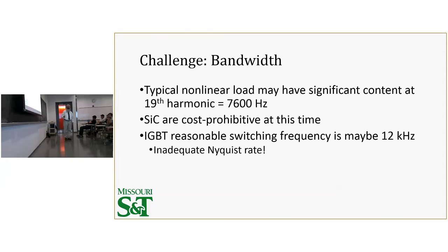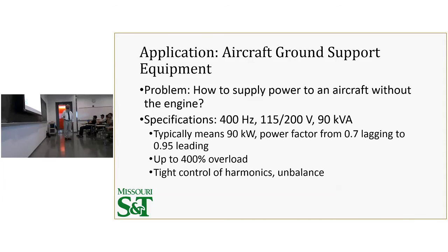Before you go, is there a specification on the timing, like for the 400% overload? Is this for a specific time? Yeah, the 400% is for like 1 second, I think. Okay, but that's still a long time from a power electronics standpoint. And it's like 300% for 10 seconds, so there is an envelope. Yeah, there's an envelope.